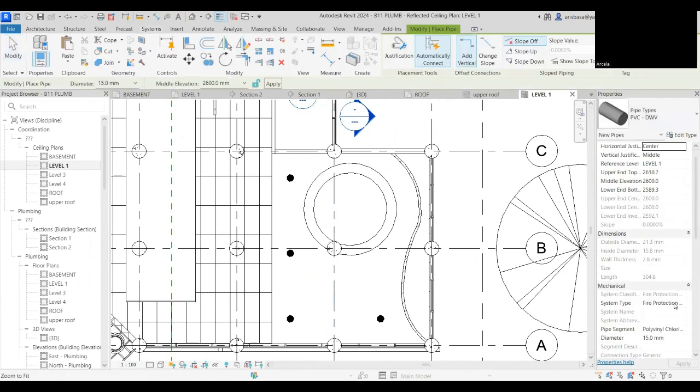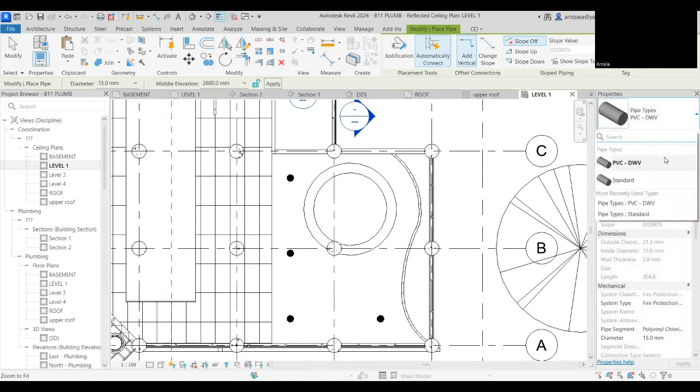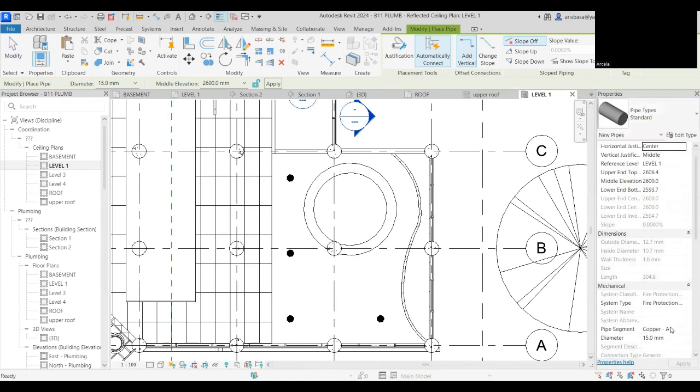This time it's a fire protection right there already, right? So this is usually the standard pipe. It should be not a copper actually, it'd be a steel. But anyway, let's make the 25 mm for the main pipe here. That goes right here. And like that.